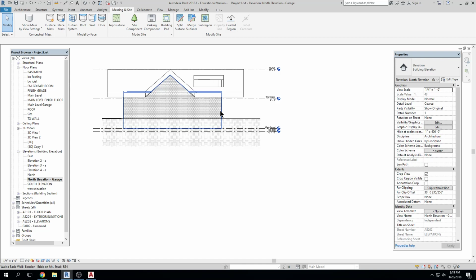So we can say finished floor is at 4,800 feet above sea level, and the roof is at 4,825 or whatever. So we can read the actual datum markers in the linked topo file, but keep our house over here at 0 and not mess things up. So we can read the actual data in the topo file, but keep our file pretty simplistic, okay?